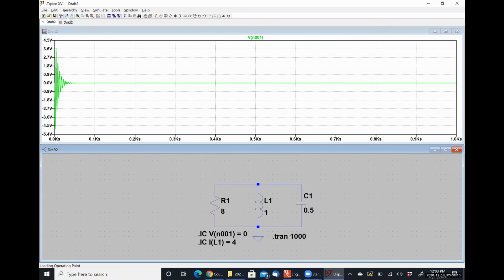I did the math in my head improperly. Alpha in this case was 0.125 per second. If I treated alpha as the effective time constant, that would mean my time constant would be 8 seconds, because alpha is 0.125 per second. Flip that over, it's 8 seconds.